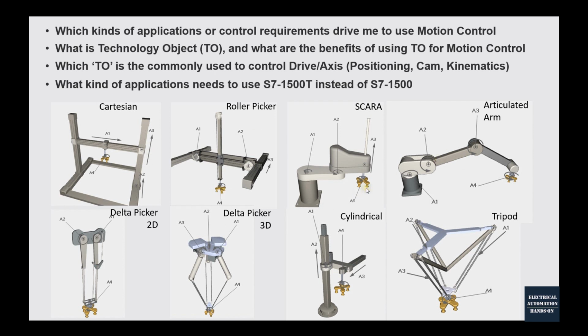After we use those models, it's very good for programming, because the only thing you need to take care of is the TCP. It's the tool center point. You only need to take care of the TCP movement rather than the individual drives, because the model already helps you to organize and manage those individual drives.